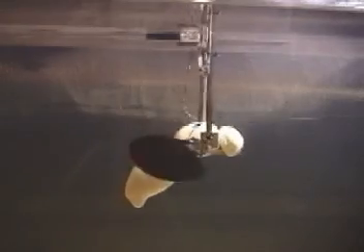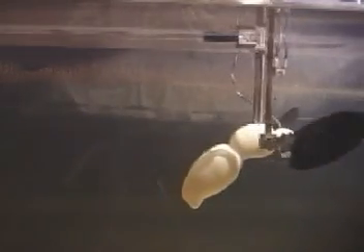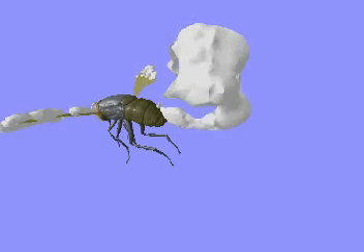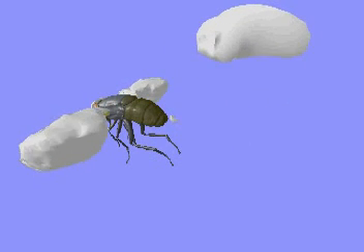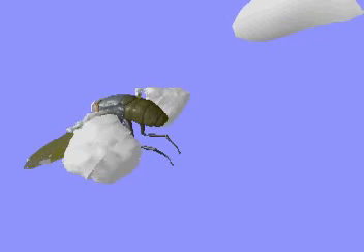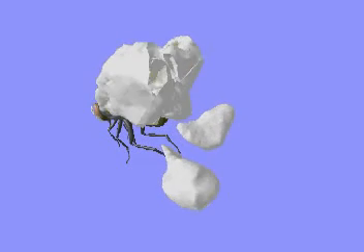So even though the dimensional size, frequency, and even the fluid are different, dynamic similarity is nonetheless achieved by matching the Reynolds number, the Strouhal number, and a third parameter known as the reduced frequency. The Mach number is very small in this flow and is not an important parameter here. In this CFD simulation of a fly in flight, the actual scale and frequency of a real fly have been used as boundary conditions. It shows the vorticity being shed off the flapping fly wings. The scaling of the simulation is 1-to-1 with the actual fly, so all the dimensionless parameters are automatically matched.